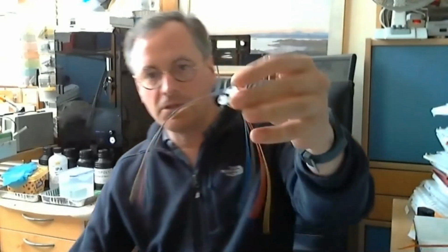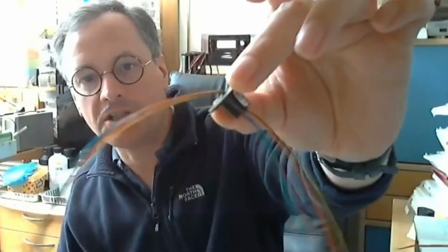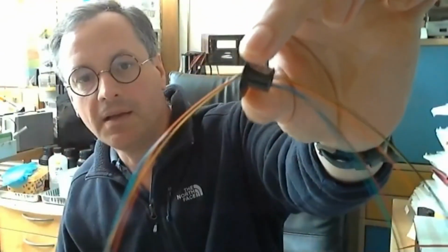And I'm using this, which is a 6-wire slip ring, to communicate with it, which gives me 2 wires for the DCC signal and 4 wires for C-bus, which means I can have as many C-bus modules mounted on this thing as possible, including servos to operate end arms that would come down and lock the ends to stop trains falling off,